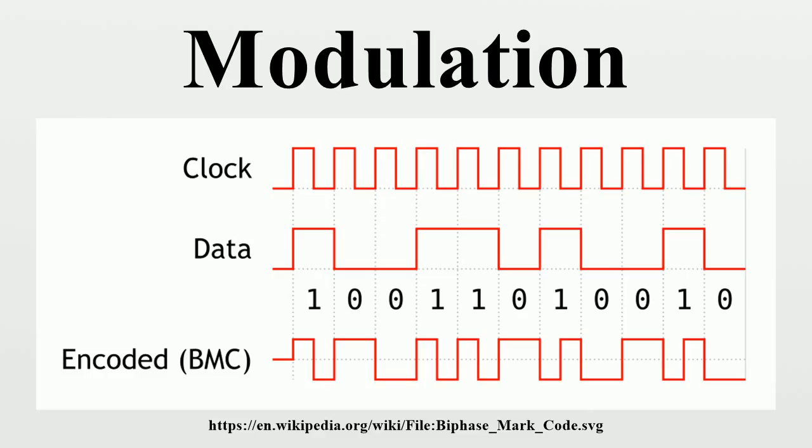Digital baseband modulation, or line coding. The term digital baseband modulation is synonymous with line codes. These are methods to transfer a digital bit stream over an analog baseband channel using a pulse train, i.e., a discrete number of signal levels, by directly modulating the voltage or current on a cable. Common examples are unipolar, non-return to zero, Manchester and alternate mark inversion codings.